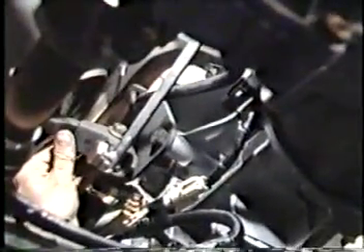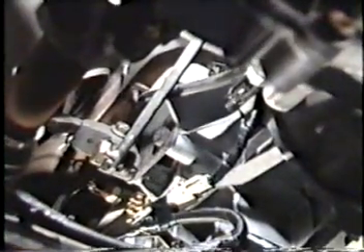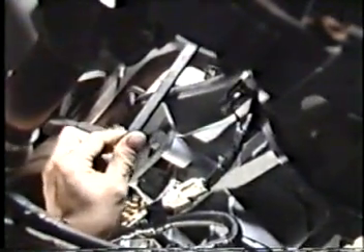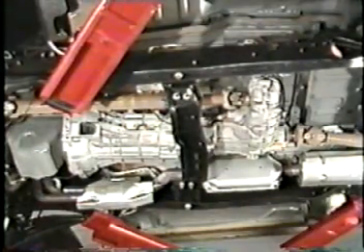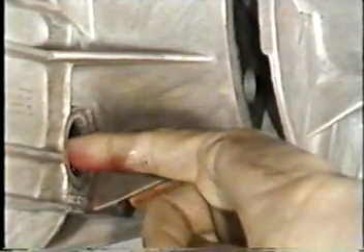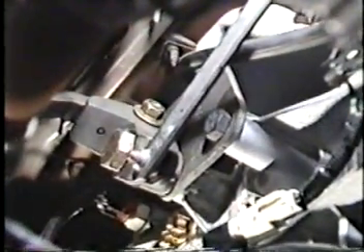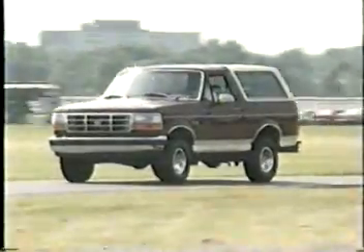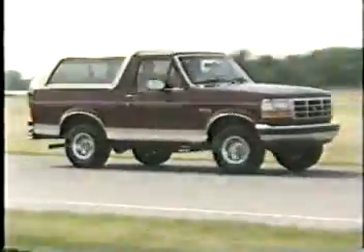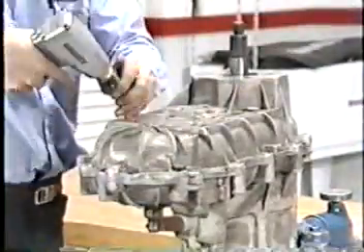With any four-wheel drive hard shifting or jump-out problem, start by examining the transfer case shift linkage. Check the linkage for binding and improper adjustment. While here, it's a good time to check the fluid condition and level, and to look for any signs of obvious internal wear or damage. In this case, fluid level and condition are acceptable. Transfer case jump out is one symptom of the problem. After any shift component repairs, be sure to properly check and adjust the shift detent plate and retest the vehicle. If that doesn't correct the problem, as in this case, it'll have to go on the bench.